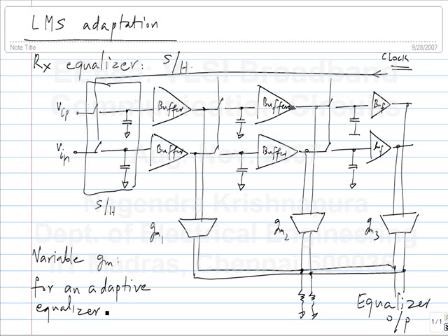Yeah, actually it's not a big problem, especially because we are dealing with an adaptive equalizer. So, we wanted, let's say, x of n, x of n minus 1, x of n minus 2, so that we can multiply these with C0, C1 and C2 and add them together, right? This is what we wanted.